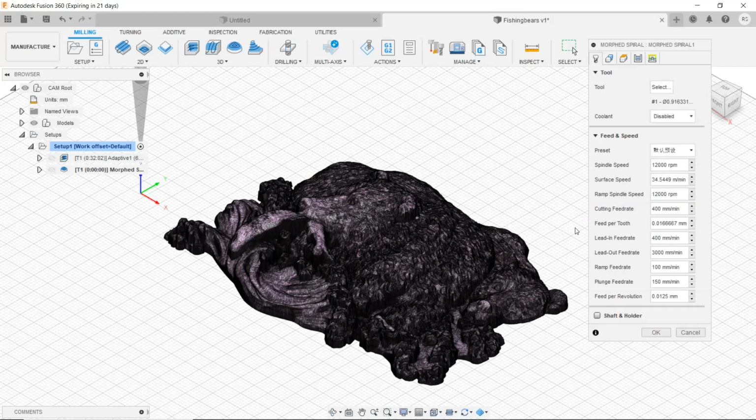Now this bit here is a lot smaller than that 1/4 inch bit, so you can't go as fast as we had on that other bit. The 1/4 inch bit, we were traveling at around 1500 millimeters a minute. With this bit here, you can do around 500 to 800 millimeters a minute. So we're going to pick 600 millimeters a minute. And that's all you need to do on here. The rest of this stuff, these default settings are just fine.